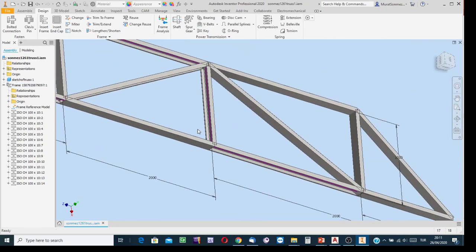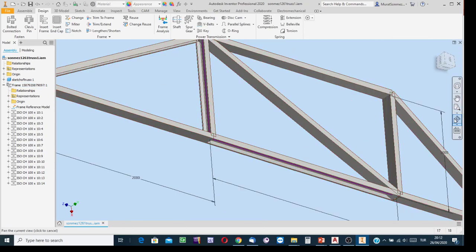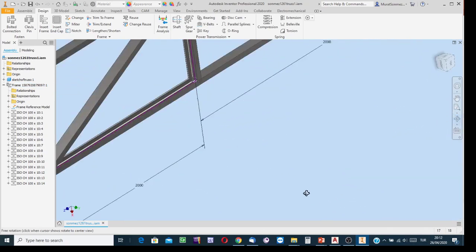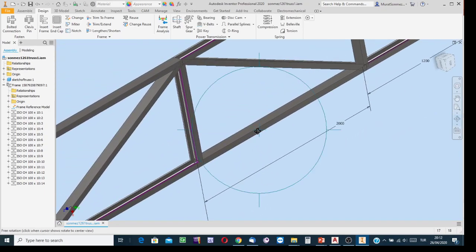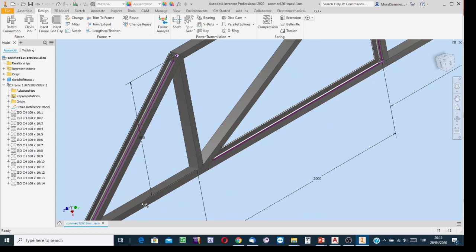But the next member, you see, unfortunately, the orientation of the next member is wrong. The C-shaped cross section looks like it has legs. In the correct position, the legs are in the up direction. But for this member, the orientation is wrong. The flat surface is at the top. Legs have been oriented in the down direction. This is wrong. For the next one, orientation is correct. This one, orientation is wrong.